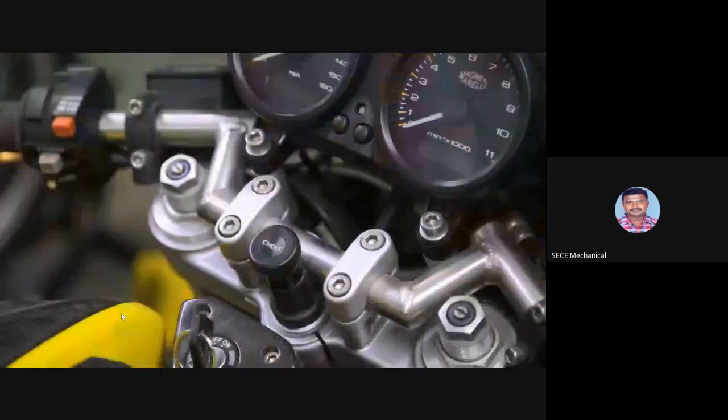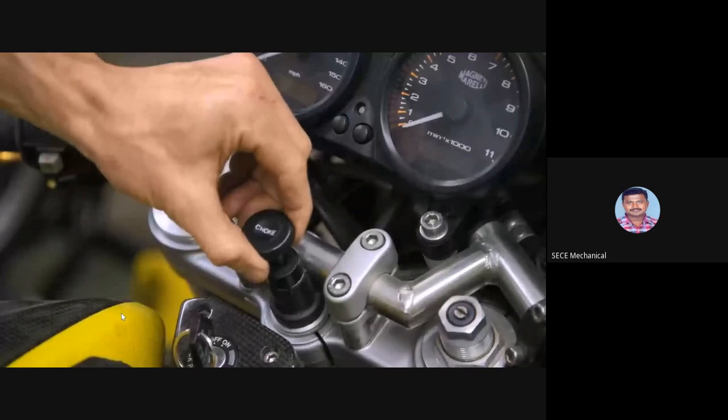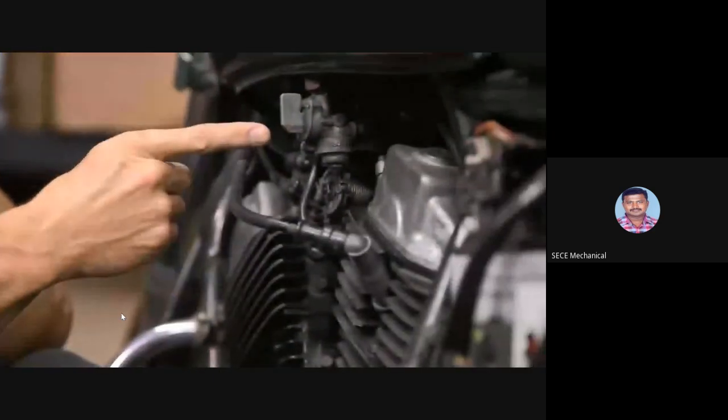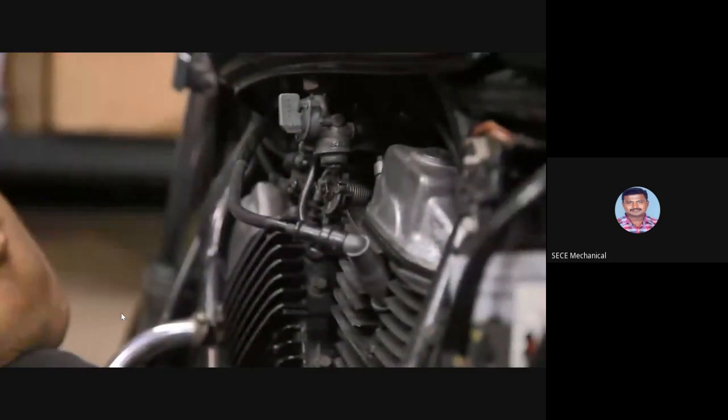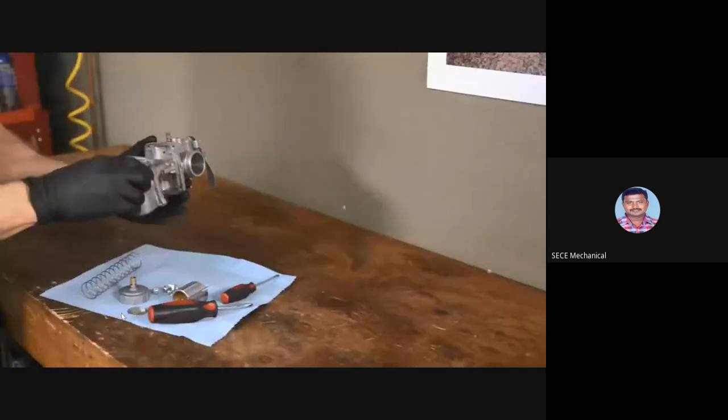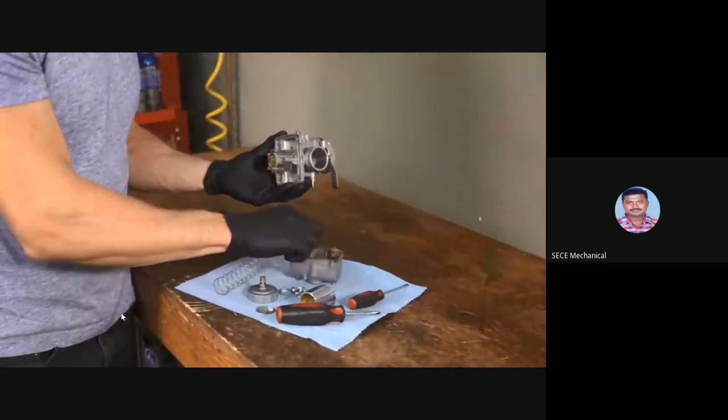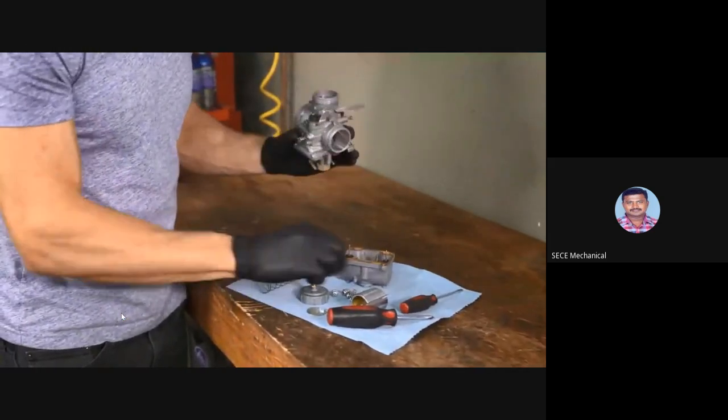Plus, with fuel injection, you don't have to deal with a choke lever on cold starts, you don't have to deal with a leaking petcock or float bowl or gummed up jets. The fact is, modern fuel injection is extremely reliable, and you're unlikely to have any issues with your fuel system. That being said, if you do have any problems, you're not likely going to be able to fix it on the side of the road, and replacement parts like a new fuel pump or throttle position sensor are expensive. Meanwhile, carburetor parts are relatively inexpensive, and these things are simple enough that you can work on them at home with basic tools.